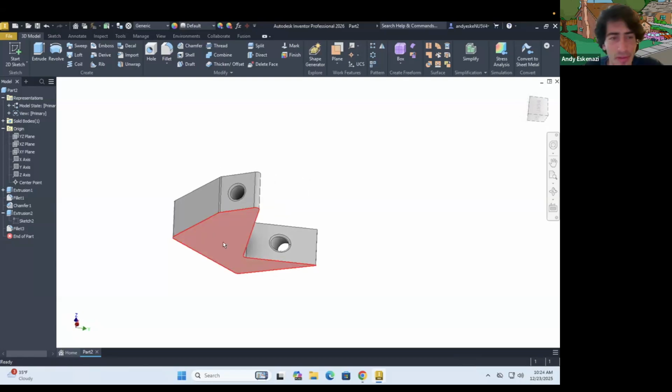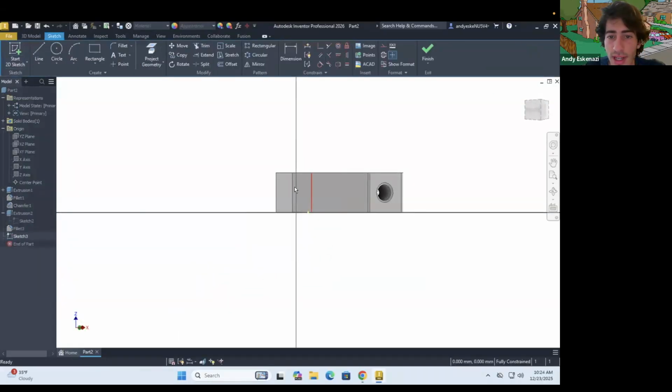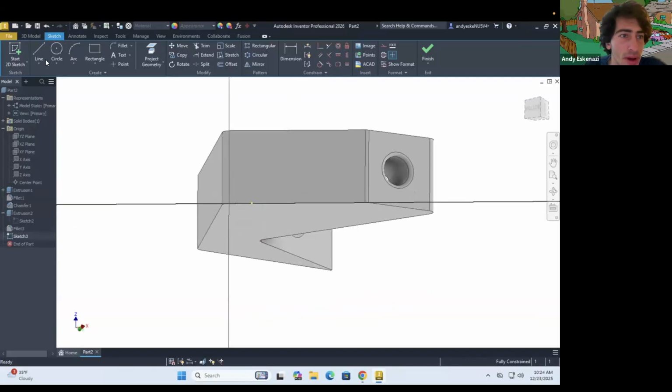Maybe let's add a couple more things, let's add more features. So I'll go here to this sketch. Now suppose that I wanted a little pentagon or some nice polygon in there. So I'm gonna do a line, and if I click in that icon right there, every single thing that I draw will be a reference line. So I can draw, I always like drawing a line that bisects a face. You see it's all fully defined.